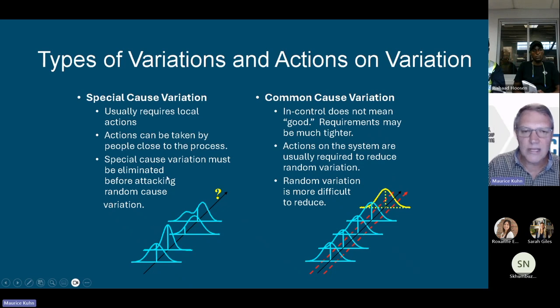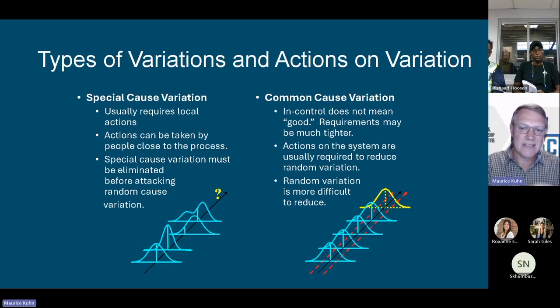And this is normally something that, if I have proper statistical process control, will show up in my control chart. Something's going very wrong in my output, and it's normally back to an attributable cause. Something we've changed. We've changed the mixture today. We've got a new person working the line. We've made a change to the machine. It's something that we've deliberately changed. And if you see that it's negatively impacting your output, unless you planned for it, go back to that thing and fix it very quickly.